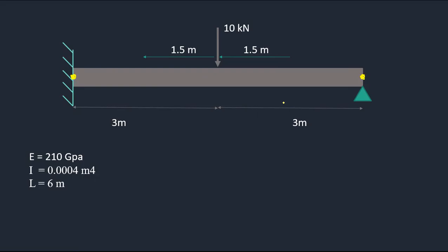only a vertical reaction at the far end. And remember you have to account for the external loading using your nodes. We will assume self weight is 0. So this point load has to be taken into consideration in our matrix calculation, which means you should have a node at that location as well. Otherwise, you can't have that load in the matrix calculation. So at least you should have 3 nodes for this element to solve.